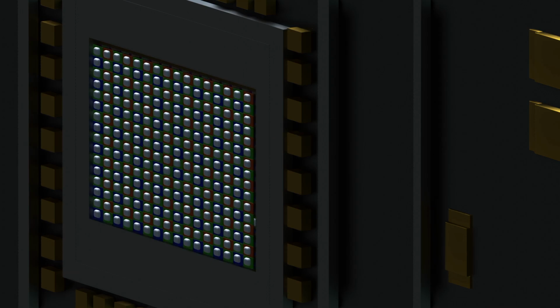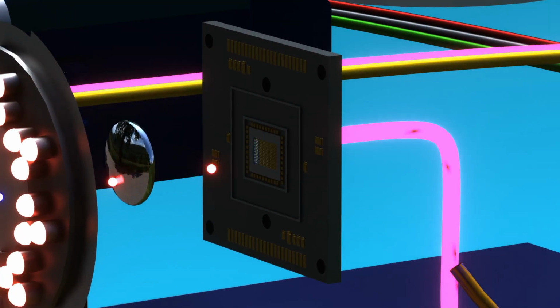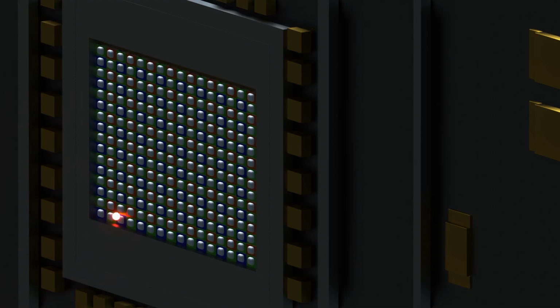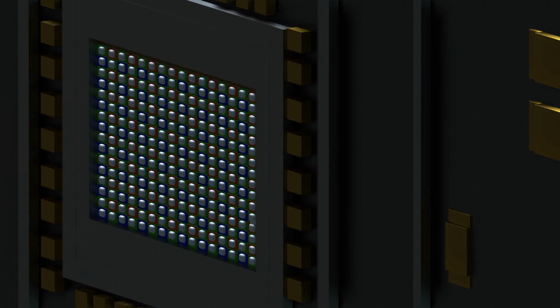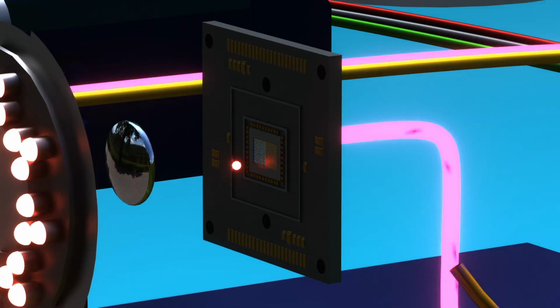Each pixel contains photodetectors arranged in a pattern. Typically, each 2 by 2 pixel group contains one red filter, one blue filter, and 2 green filters. Since there are only 3 primary color filters, but 4 photodetectors in the 2 by 2 arrangement, one color must repeat. Green is repeated because the human eye is most sensitive to green light. This arrangement is called the Bayer filter pattern. In this pattern, blue and green appear on odd rows, while green and red appear on even rows.